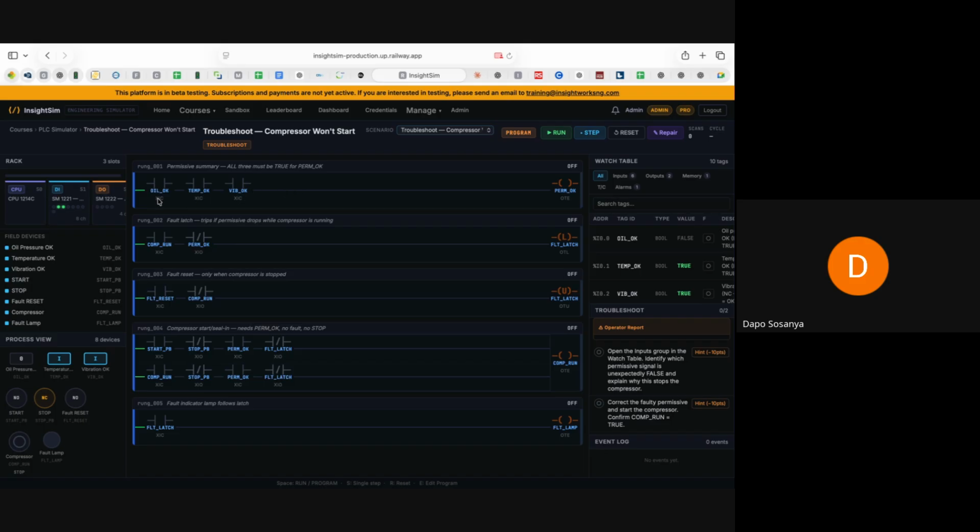And then you can see this is oil_OK, temp_OK, vibration_OK. This line is implementing the permissives. That is rung 001. All three must be true so that you can have a perm_OK. That is, permissive is OK.